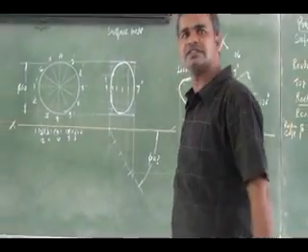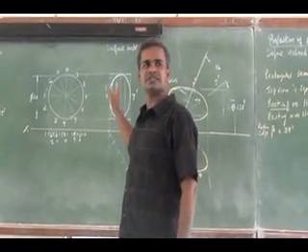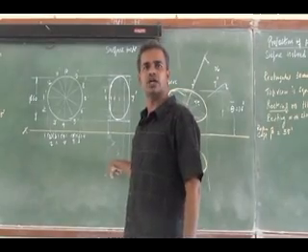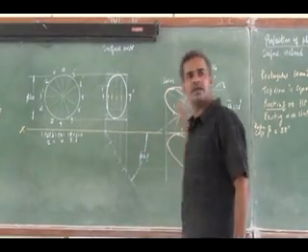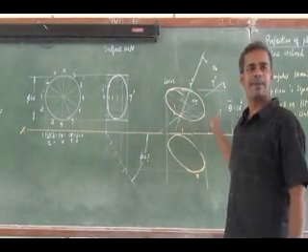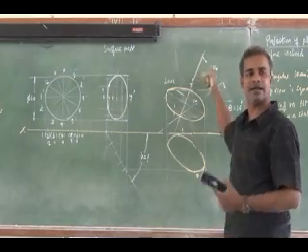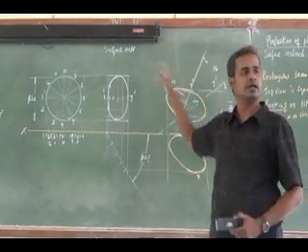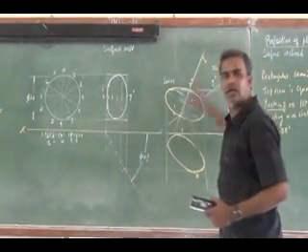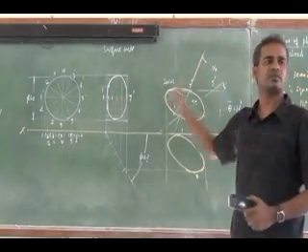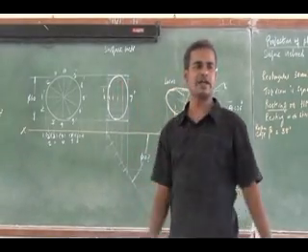See here, this is the difference you have. Here, the hexagon is given as the ellipse. Instead of giving the surface inclination to VP, in the third step the apparent inclination is not given. Again, true inclination is given. So from the true inclination, you have to find out the apparent inclination, using the straight line concept. Along that apparent inclination, I have to reproduce this front view, the ellipse. Then you can go for your final top view.